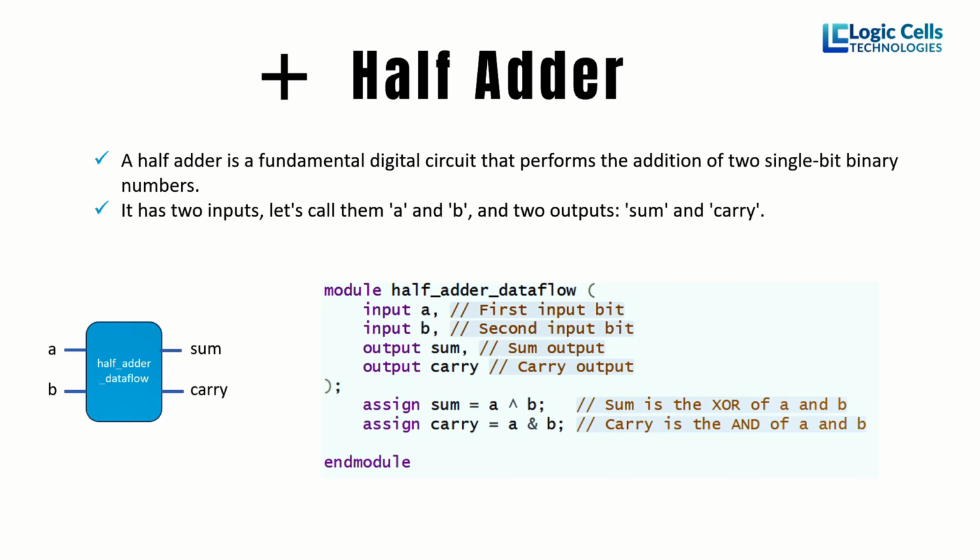You need to understand Verilog scheduling semantics. In Verilog scheduling semantics, there are 4 stages. Scheduling semantics mean which things execute first, and which things execute in the next stage. The very first stage is active, meaning all the active statements will execute first. One of those active statements is the assign statement.